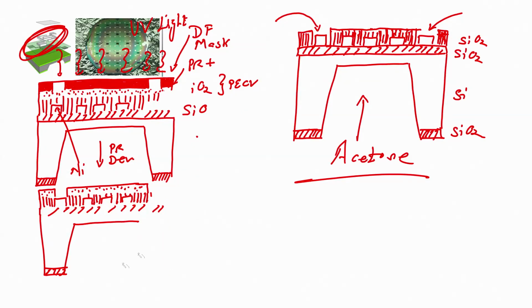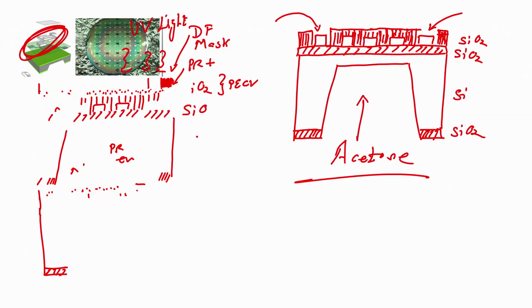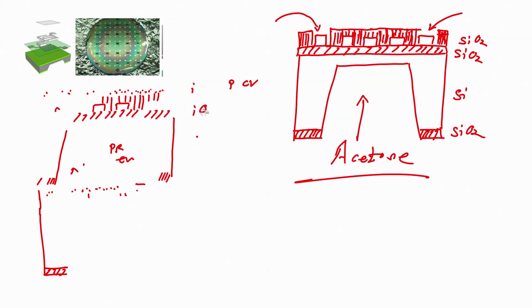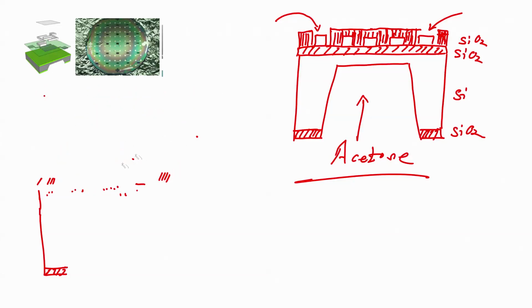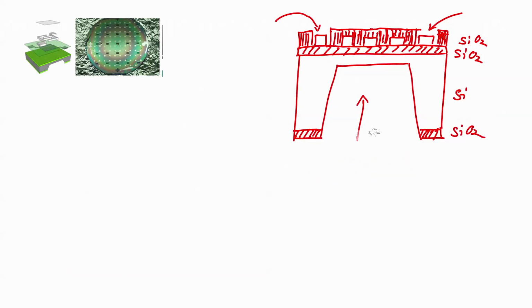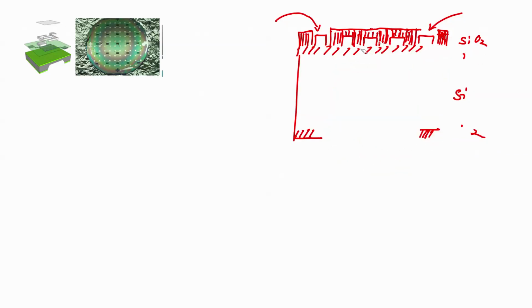Now, we have an insulator, right. So, we can now deposit a metal that can be used for fabricating interdigitated electrodes. So, what is this metal? Let us use aluminum as a metal for fabricating interdigitated electrodes. So, we can start from a wafer.